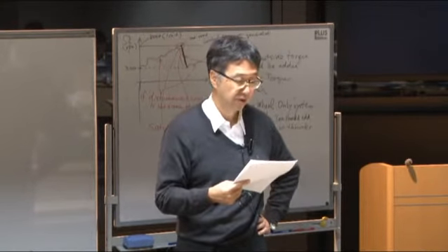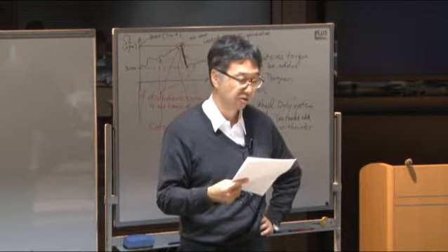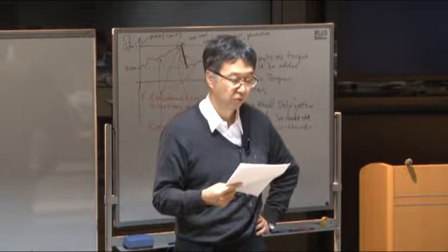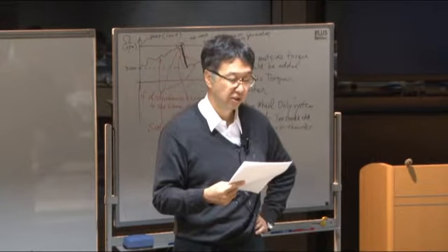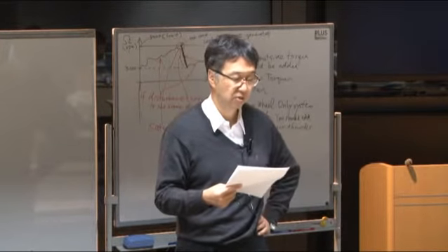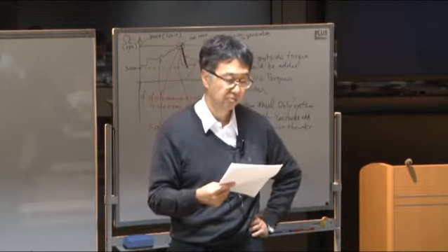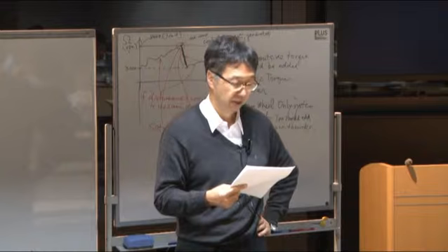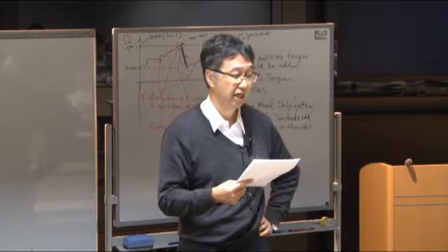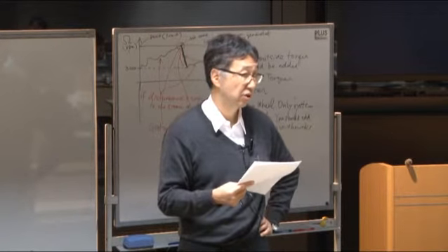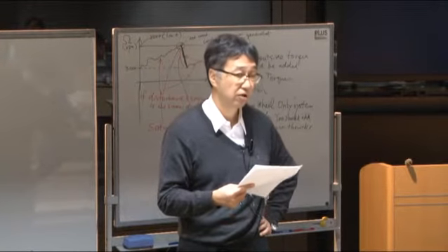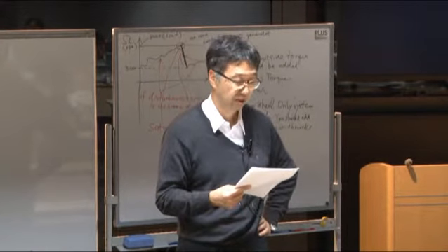And please see the fifth one, that is an international communication satellite. Roll and pitch are 0.11, and the yaw axis is much degraded, just 0.3. Okay, it is a much relaxed requirement. And why? Why does the yaw axis usually get a lower accuracy requirement? Why?